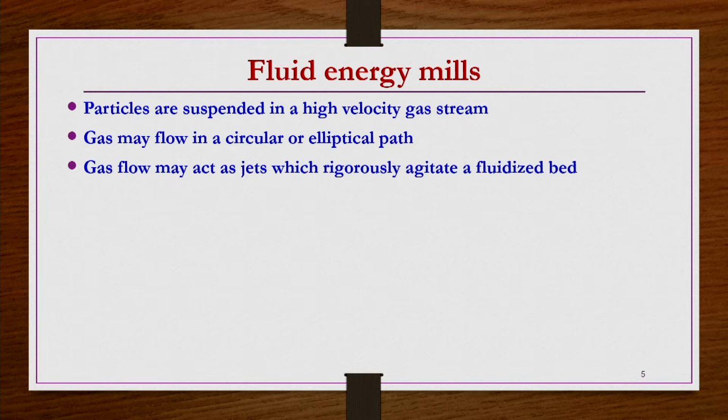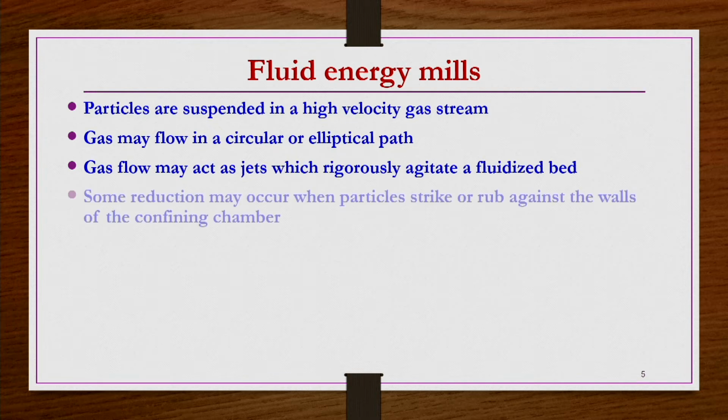Okay. So, whatever the gas flow or the steam is there, that will act as a jet which will vigorously agitate the fluidized bed of solid particles which are to be reduced. Because of this agitation, there will be attrition amongst the particles. There will also be attrition between particles and the walls of the container. So, the further reduction of the particles takes place.